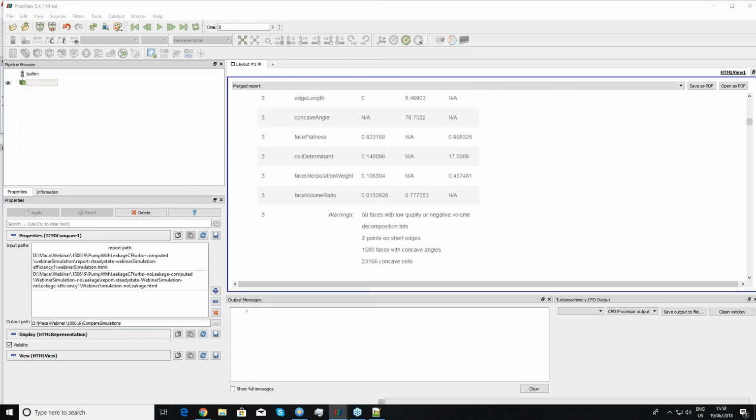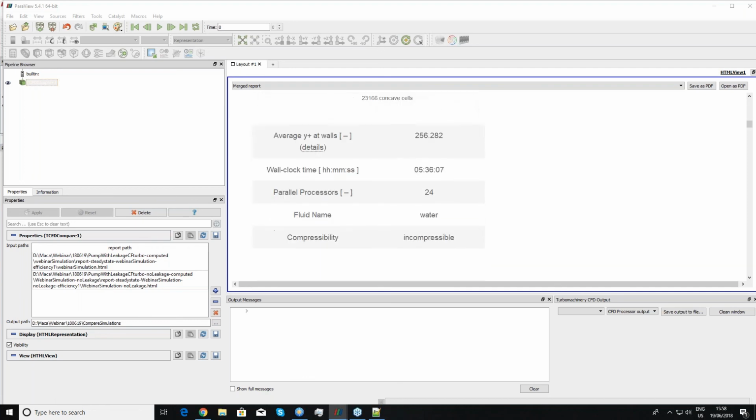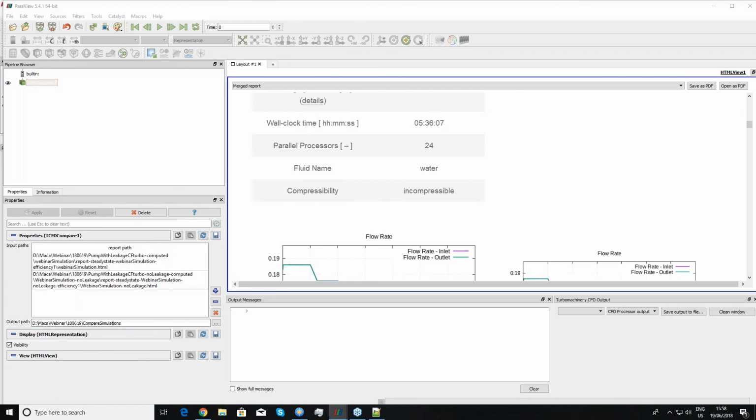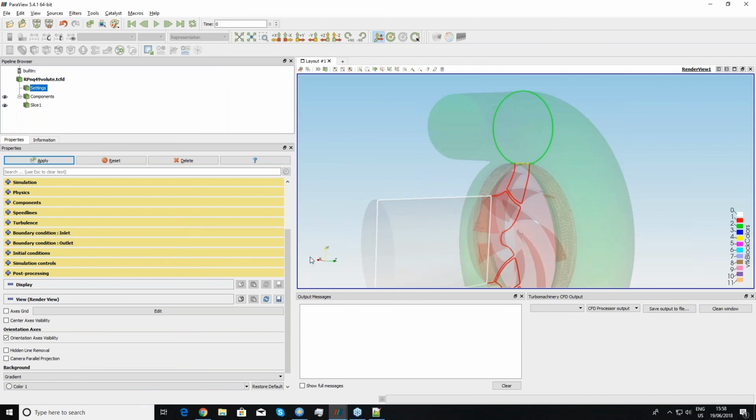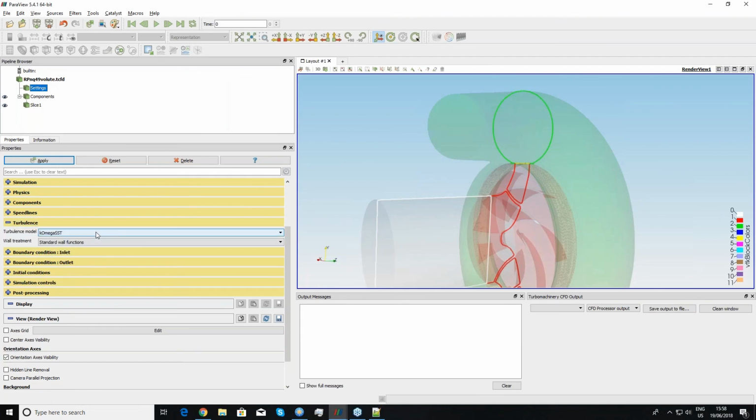Okay, thanks. Another question. Hello, can you manually change the turbulence model, k-omega, k-epsilon, and interface settings for frozen rotor or mixing plane? So Radek, would you answer this also? Yes, I will. Okay, so back to the setting part. First was the turbulence modeling, right? The turbulence models are preset here, the basic one or the implicit one, but you can also use another one. There are many others, so if you want to use some favorite which is not here, it can be scripted easily.